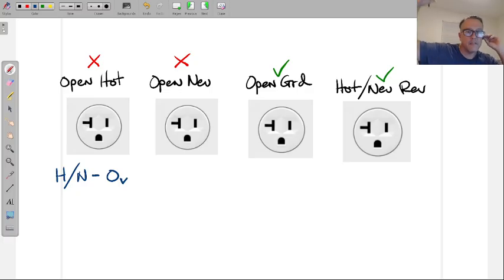Now, the more expensive the meter, the better it is at being able to distinguish when something is not operational. If you just have a standard meter, and I'm not saying a cheap meter, but just a regular basic operational meter, nothing in the $300, $400, $500 range, then your meter still struggles and tries to give you a number. It's trying to sense, and there's a lot of little micro things going on inside. So that's why I say the number could be something strange, but it just simply is not 120.